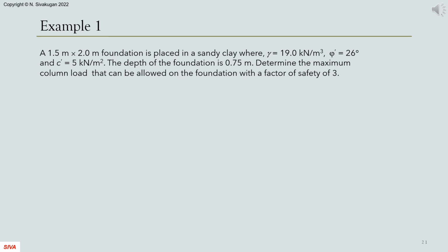First step is to always carry out the plane strain correction to the friction angle. Use this corrected angle in determining the bearing capacity factors. Then, determine the shape, depth, and inclination factors.